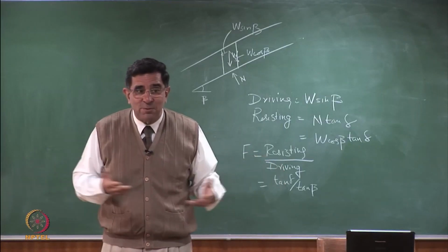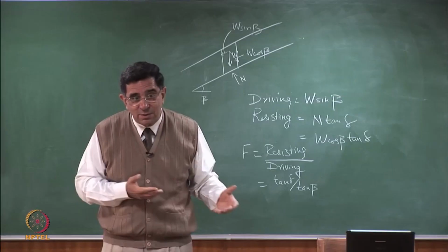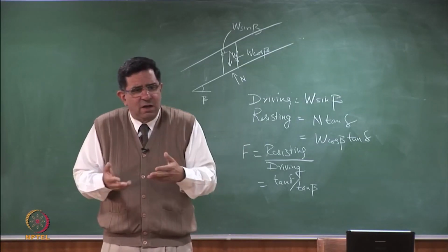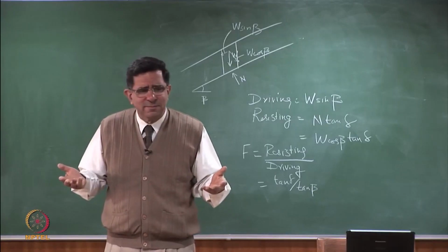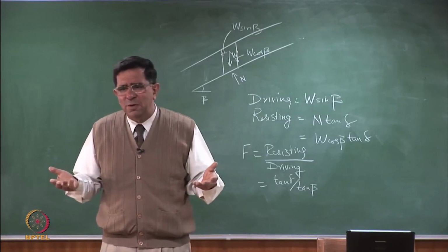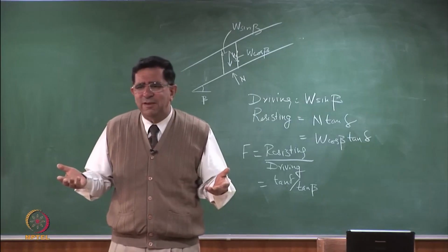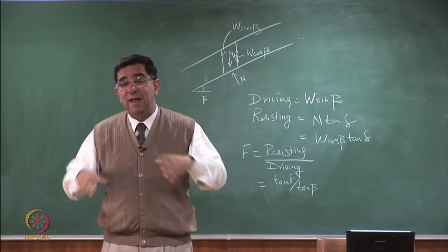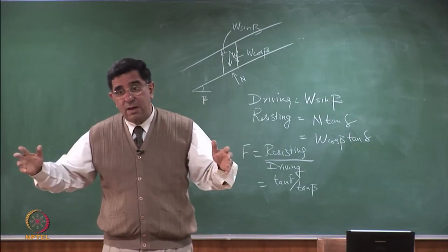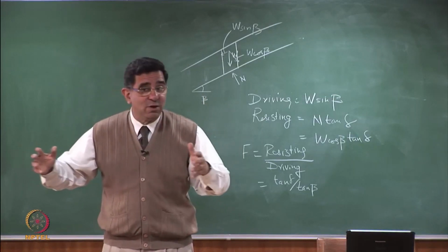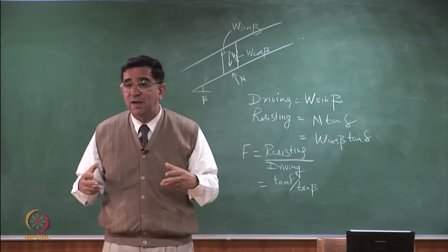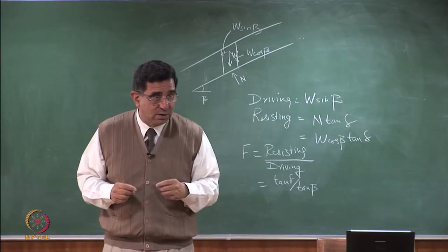And do remember that you are putting the landfill on a geomembrane. And designers like us have been originally saying base is flat, so let's have a smooth geomembrane, or maybe it's only tilting at 2-3 degrees, doesn't matter. But what we've seen over the years is that landfills can move along the bases, especially if leachate head collects inside the landfill due to accumulation of water.